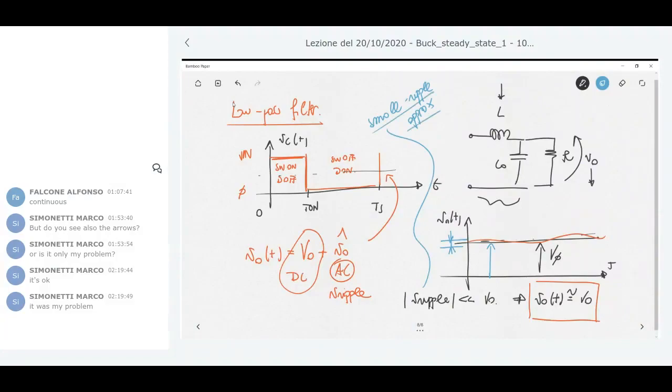You always have to think that we have to manage real circuits, and in practical circuits, filter action is not perfect, and so the output voltage is not a perfect DC voltage, it has some ripple imposed on it. But anyway, in a well-designed converter, this ripple is made to be very small. This kind of quantity, the ripple superimposed onto the usable DC quantities, is typically a specification that the designer should consider in the design.